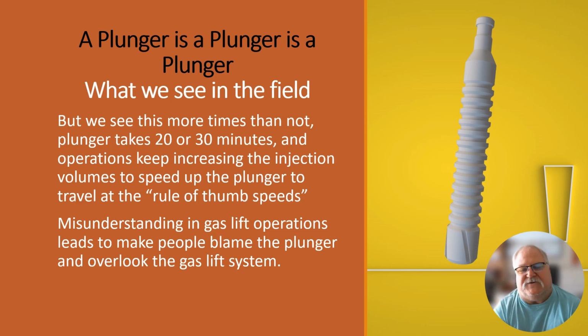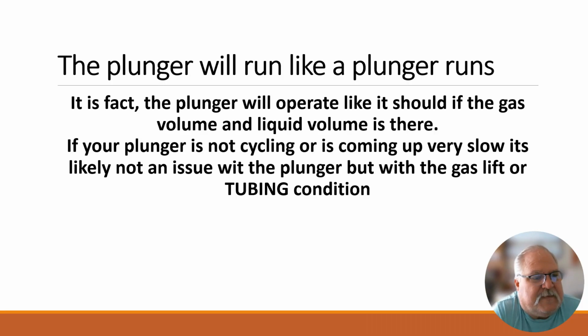And everybody goes right to the plunger and says, oh, we've got to pull the plunger up. Well, the first thing is, if you've got to pull the plunger up, what does that tell you about where gas is being injected? It's not where you think it is. Nothing to do with sitting at 55 degrees or any of that stuff. It's all about understanding where the gas is going. And that's the number one mistake most operators are making. The plunger will run like a plunger runs.